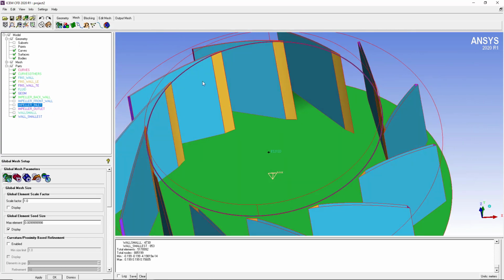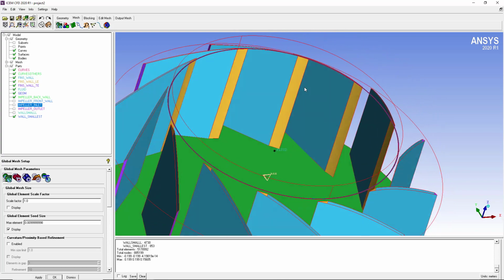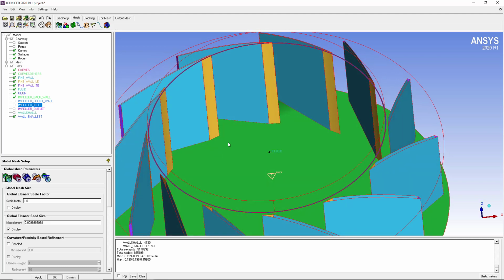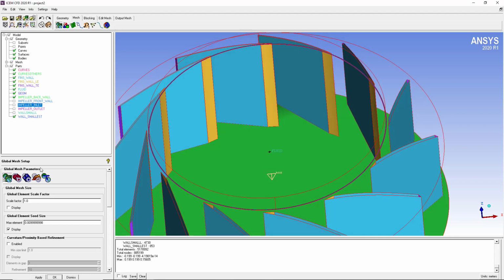And generally speaking, when you set the size on all these surfaces, this will be influenced by the sizes of the surfaces in the volume size. And just a reminder for you, the octree starts with one big tetra that covers all the geometry, and then it divides up so that the algorithm inside the meshing software will capture the geometry features, and after that this will again go back and move forward to the volume, and then this will be stopped when the maximum size is achieved anywhere inside the volume. So this is the thing we are going to do.